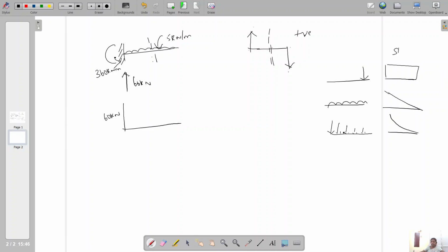This is for the shear force diagram. For the bending moment diagram, it is one step upward. For a point load you get a constant variation in shear and linear variation in bending moment. For a UDL, you get linear variation in shear and a parabola in bending moment. So we get a second degree curve for the bending moment.